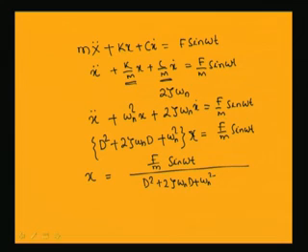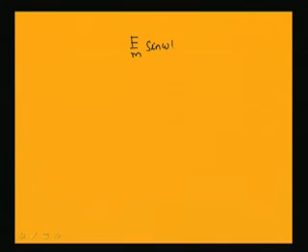For a system with sin omega t in the numerator, the solution can be obtained by substituting D square equal to minus omega square. By substituting D square equal to minus omega square, this equation reduces to f by m sin omega t divided by minus omega square plus 2 zeta omega n D plus omega n square.